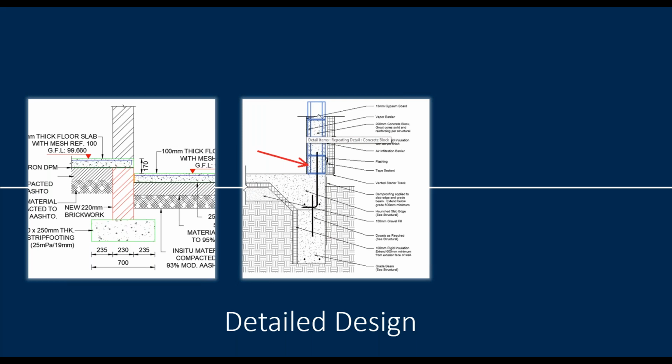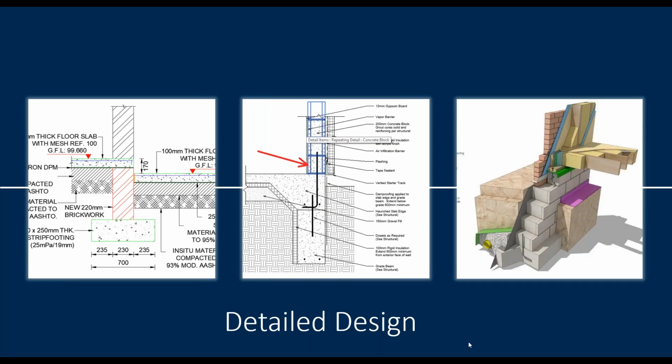And so if you wanted to take it a level up from that, you could have literally everything modeled in 3D and then add tags to it. And each of those 3D elements has got information attached to it. That is, in my opinion, not always necessary. I mean, you don't have to model waterproofing as such. I tend to prefer to stay in the middle bucket over here, where you've just got the detail items that have the intelligence that you need for the tags, but you don't necessarily have to go and model it in your 3D model.